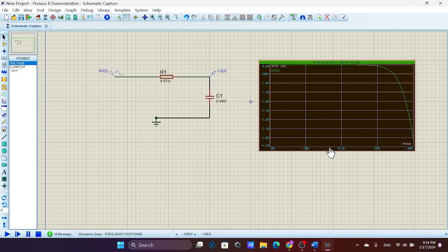For the graph, it shows that at -3 decibels, the cutoff frequency is equal to 800 kHz, and here 800 kHz, which means that the low-pass filter was simulated properly and the input signal will undergo the low-pass filter, which causes the frequencies above the cutoff frequency, -3 decibels here, to be filtered, becoming smooth and preventing high-frequency noise. And that's all from my part.